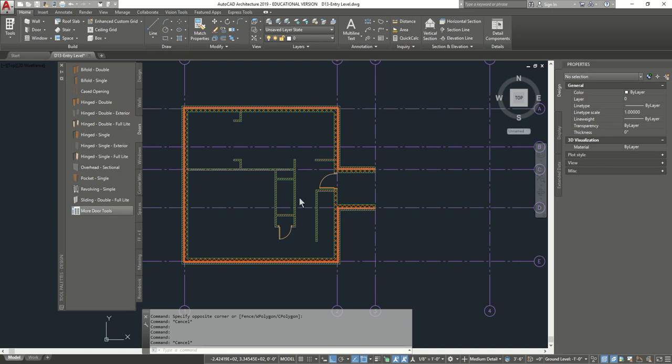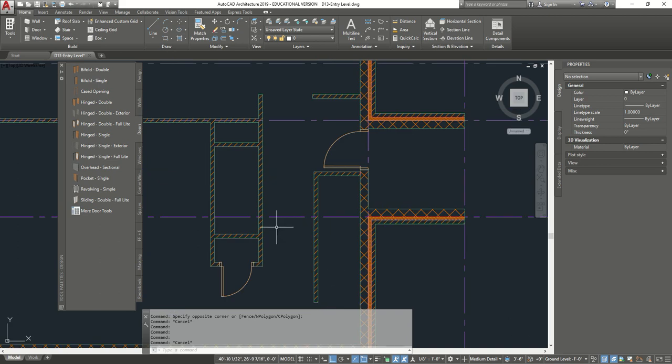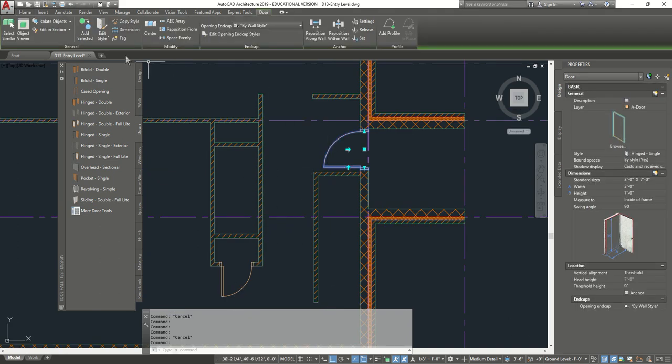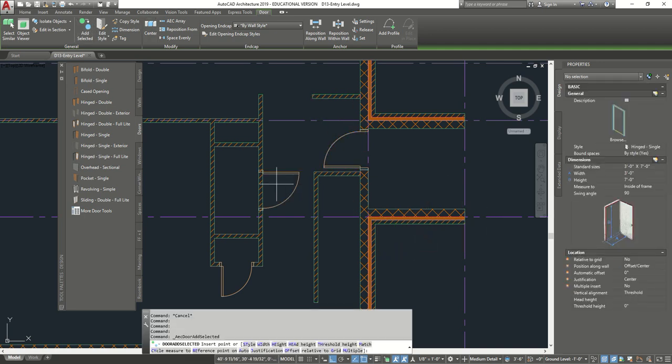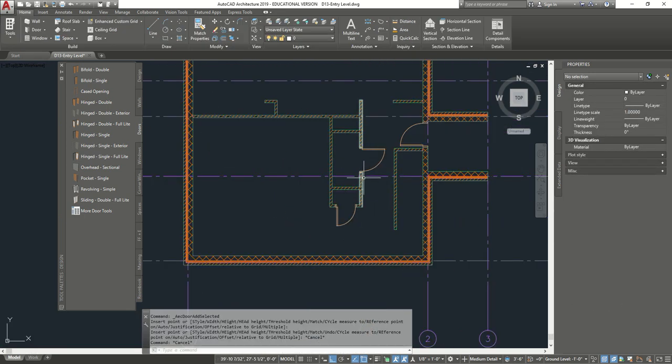Alright, so we add doors. We could also add another door here. I think we're adding one here. Just give me 1 second to look ahead. So we're going to add another door centered, so same door that we have here. We're going to add selected. We're going to use this wall here, and it's centered to the middle. So we have another door placed here. So total, we should have 1, 2, 3 doors.